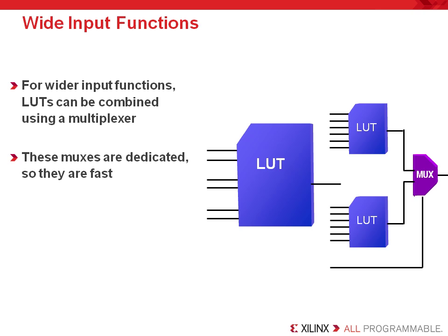For wider input functions, the outputs of 2 LUTs within a slice can be combined to make larger combinatorial functions, such as a large mux. In this case, a 13-input function of limited functionality can be made. The beauty of this resource is that it saves extra LUTs from being cascaded in series, which, as I mentioned earlier, will likely hinder system performance.